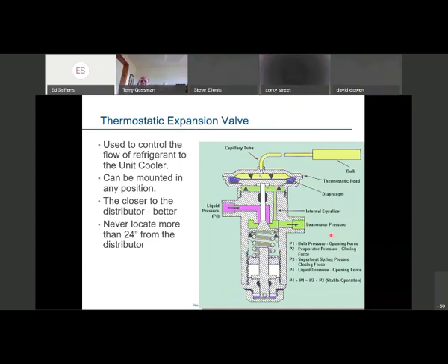However, at low load conditions, and we talked about load the other day, if our expansion valve is oversized, we could possibly flood back to the compressor and create some flood back, like what Kevin talked about. Now, this being an internal equalized expansion valve, we want to use it for systems or evaporators that have no pressure drop across the evaporator.